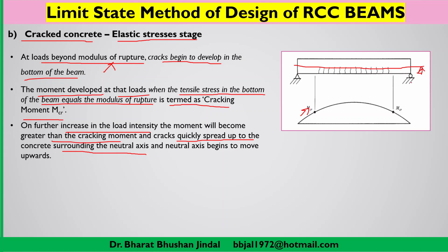upwards. That means from the bottommost fiber of the concrete member, cracks will start propagating towards the neutral axis, and the neutral axis begins to move upward. So later on you will be able to understand what is the meaning of this neutral axis movement.